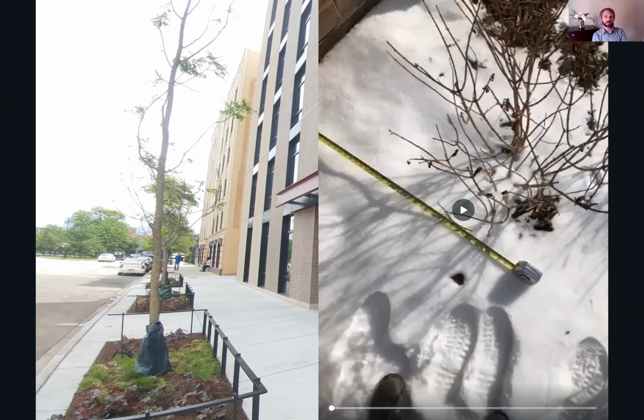At least 18 inches is where LEED gives you a point, but as far away as we can from the foundation of a site, so that way we don't have water entry and pest entry and all that. So again, when you're doing your landscaping plan, try to get any kind of plants, even grass, away from the foundation and the base of the project.